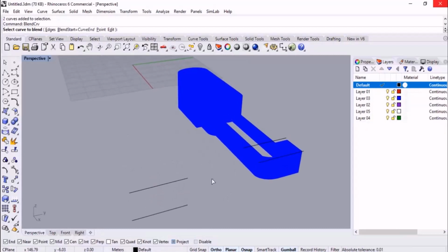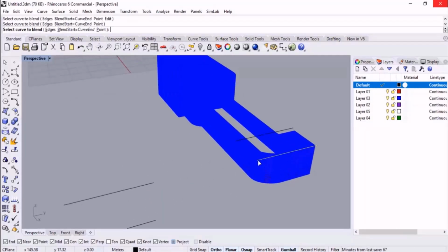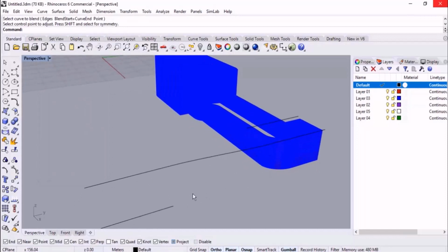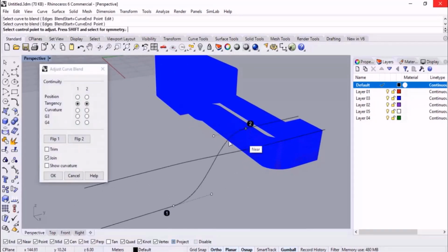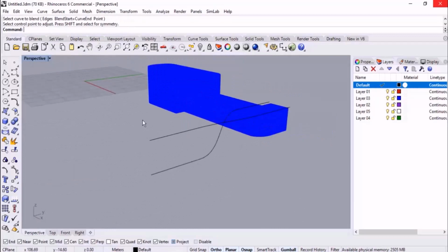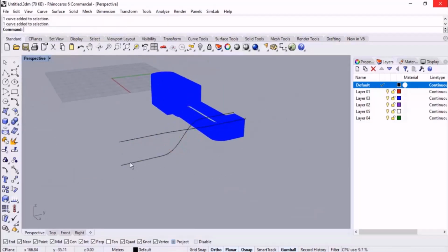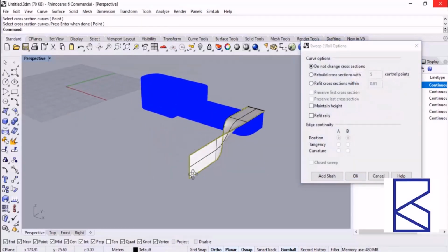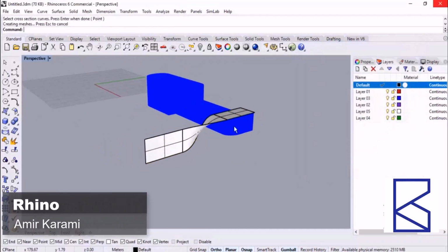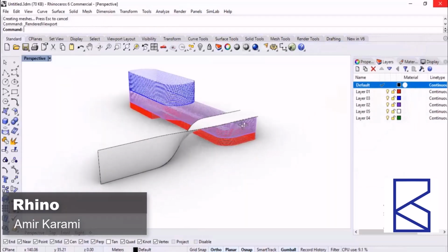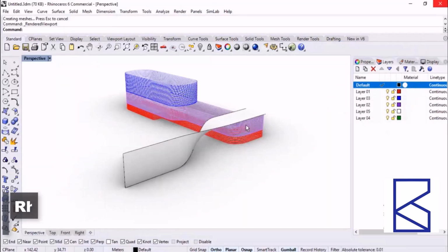And then what is left is a blend curve. I start the command of blend curve. I select the curves to blend them. Check this out. This way, like this, we can blend them. In the future sessions, you'll learn extruding these geometries too, which is very simple. I mean, we will talk about sweep rail and others for having masses and surfaces. Guys, don't forget to practice and take notes. Try to sketch the project on your own.